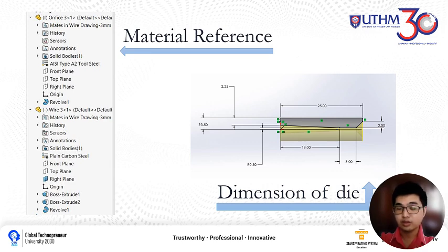This is because for the wire cone surface to fit inside the die, the contact surface must be bigger than the wire surface, to prevent deformation on the biggest diameter of the wire. So it won't deform when being pulled and stuck at the inner surface of the die.